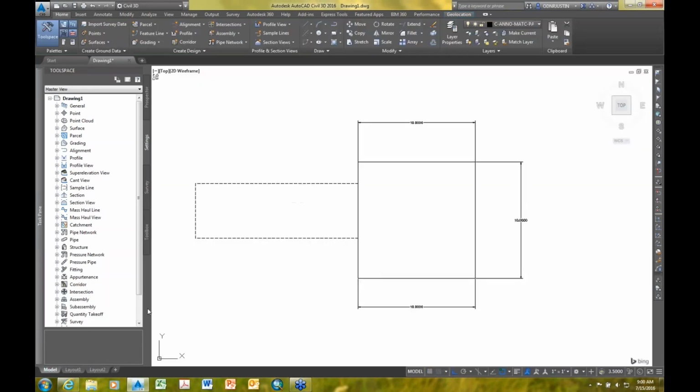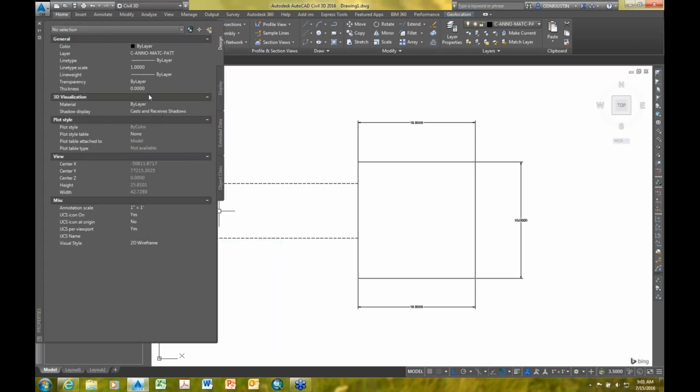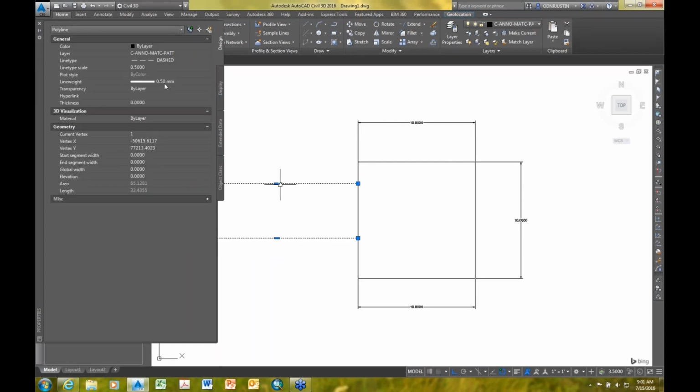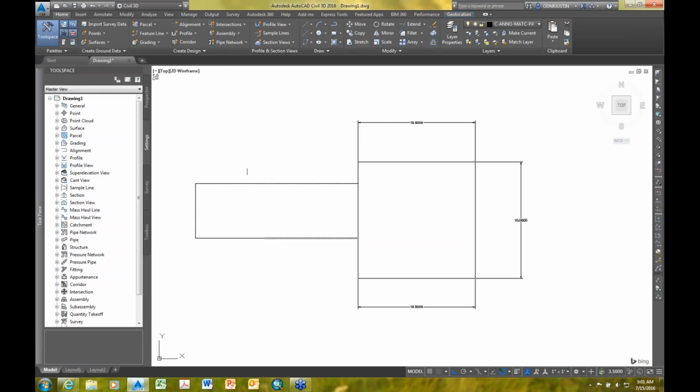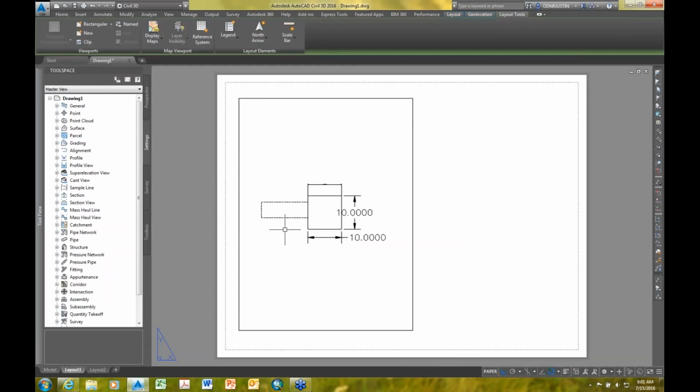That ends up being a cat and mouse game to me, where you go back and forth trying to get these right, and you'll eventually get to a point where if I go back to properties, select it there, change this to 0.1, you'll end up with situations where the line looks solid here, and if I go to my drawing, it's dashed just like I wanted it.